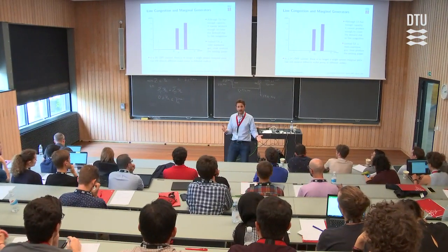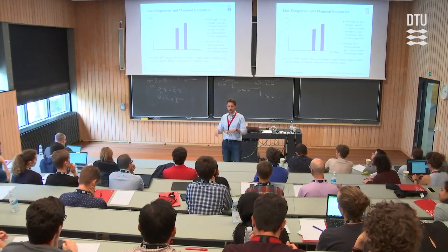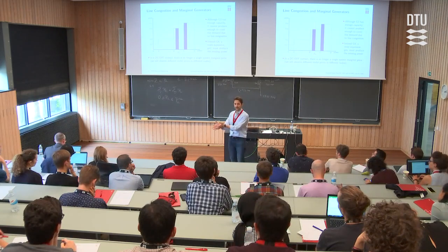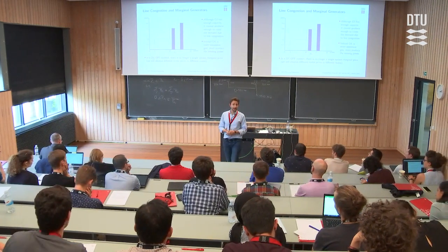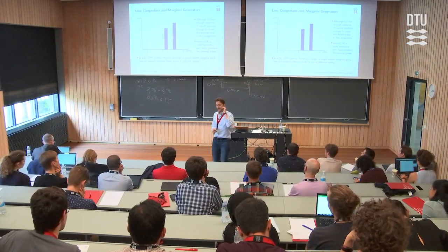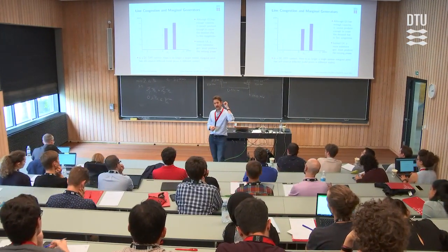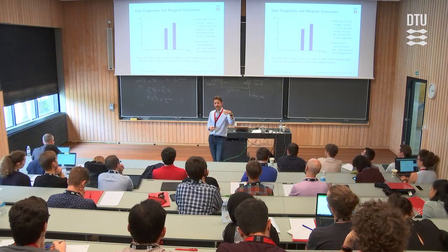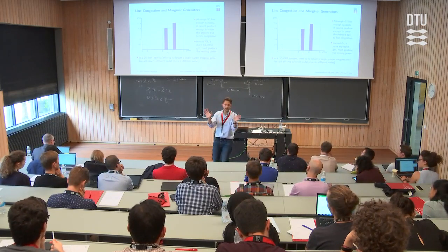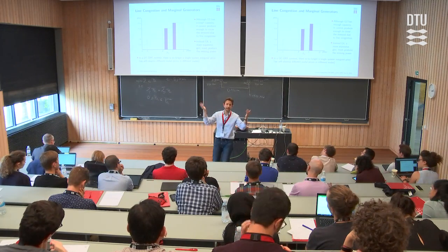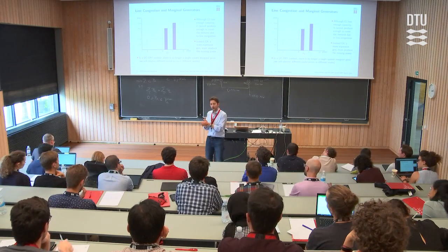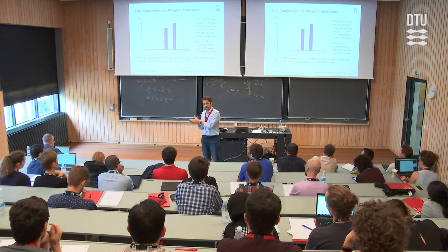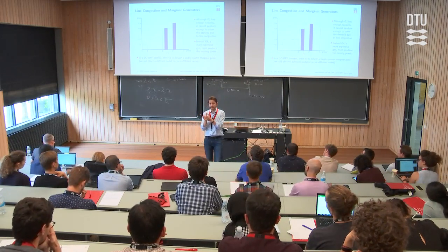We have the market dispatch, and then the operator takes these values and puts them in the system, and they have an estimate about the load, so they have an estimate about the losses, right? And I'm going to that market, and I am buying for the next day. Actually, I don't know the dispatch yet, but I have an estimate based on historical results of what the losses are going to be for the next day. So I'm going and buying from the market this generation to cover my